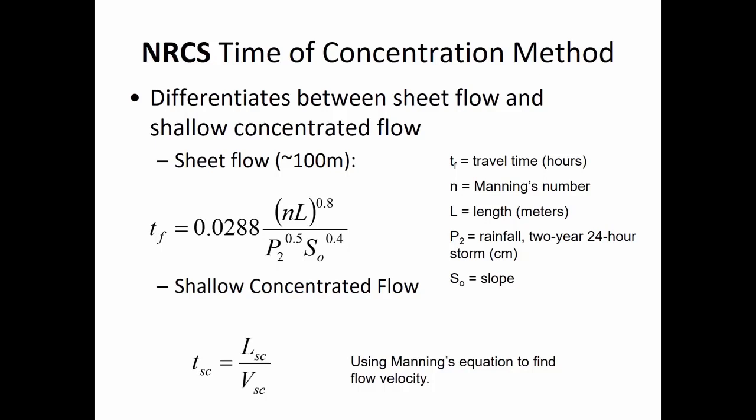And so the rain gauge, when it starts to sense that precipitation is beginning, it measures with a tip every time a certain amount of rainfall occurs, and the sensor knows when it's raining, and the stream gauge that's in the river knows when the water starts to rise, like when the stream is getting deeper. And so then after the fact, what you can do is download the data and just look at when did it rain compared to when did the river get deeper. And the difference between the two is the time of concentration. And so that's a physical measurement of it.